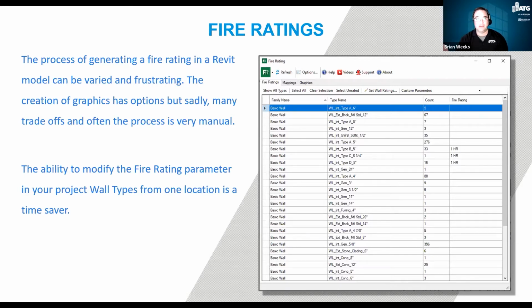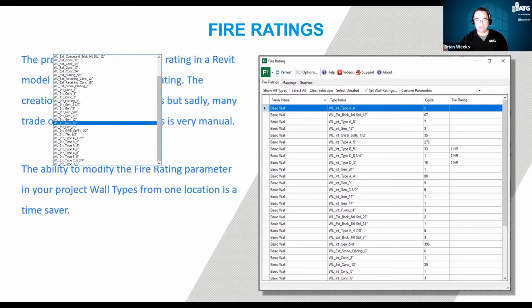So talking about walls, like I said, each wall type within Revit has a setup parameter, and you have your fire ratings as a parameter within a wall type. That's just a default setting. If there's not a particular fire rating associated with a wall, the traditional sense is to go in and select that fire rating and apply it to that wall type.